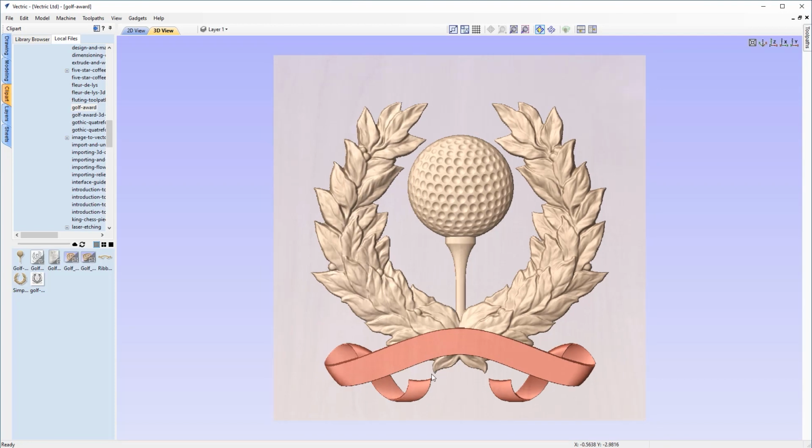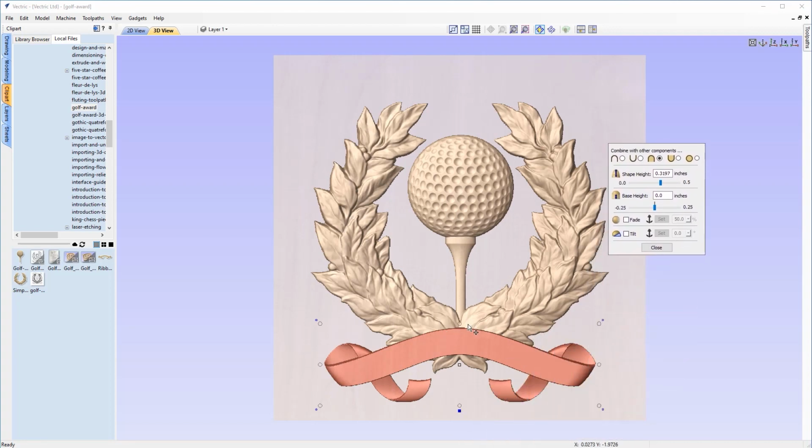So that looks like it'll give us enough of a gap there, but in changing the shape of the component there, if we just go back into the component properties, you'll see that it's actually changed the shape height because we've essentially stretched that shape out. So after we've adjusted that, we just need to set that back to 0.3, press space just to accept that, and then we can close out the form again.